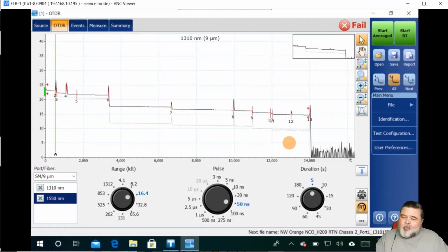So back when I was working in fiber, there were more manufacturing and cabling issues. We're seeing much less of that occurrence, with the quality of the manufacturing that we have today, but we are still seeing a lot of cable placement issues, a lot of environmental issues that contribute to some of these problems. And so it's still very important to troubleshoot this kind of stuff, right? So it's important to understand that you need to look at these bidirectionally, ideally with two wavelengths.